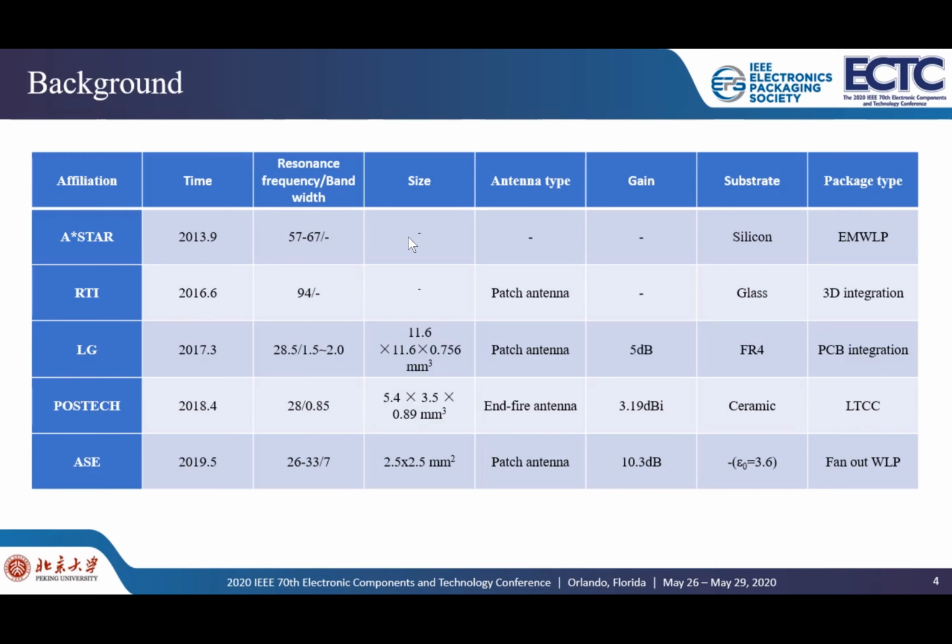This antenna has a multi-metallization level glass substrate vertically, which includes a radio frequency interposer and a patch antenna, and the silicon germanium BiCMOS beamformer chip is integrated under the antenna.